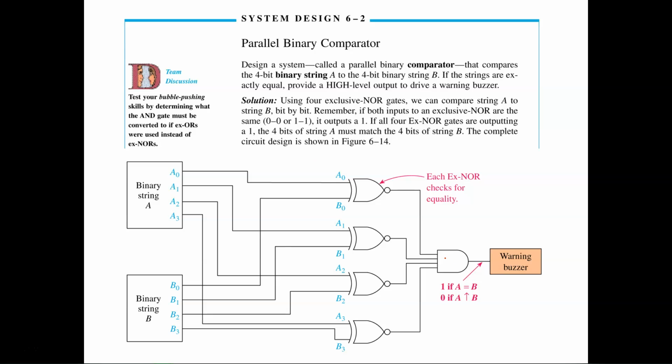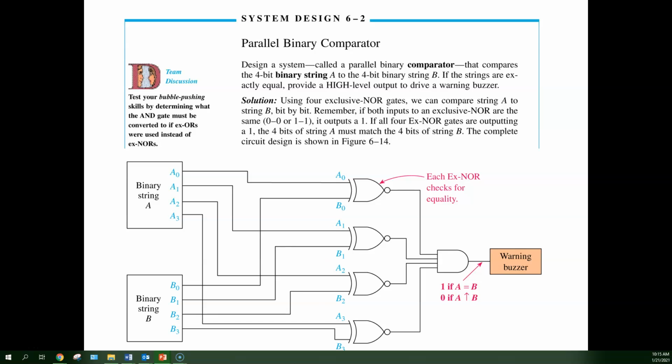So that would mean, to be able to get a signal here, what do I need to do to get no signal out of here? Have these guys be totally different, right? My signals have to be different for this guy to pass. No, I'm sorry, my brain decided to check out. So in order to get a 1 here, since this is an exclusive NOR, both signals have to be the same. That means in order for this to come on, your signals have to be the same for all of these.